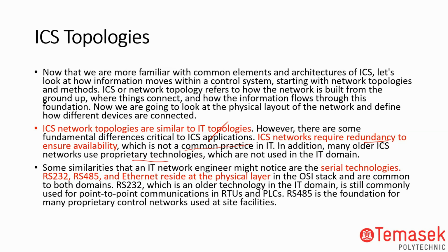Next thing is there are a lot of serial technologies out there. Still today, there are a lot of serial technologies such as RS-232, which I mentioned just now. RS-232 is point-to-point. 485 is multi-drop, basically allowing one to many. And then Ethernet is a modern one. As I mentioned, this goes from the 80s, 90s, and then 2000 for your Ethernet. So every 10 years or so, an improvement comes in.